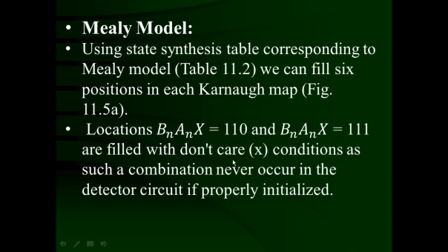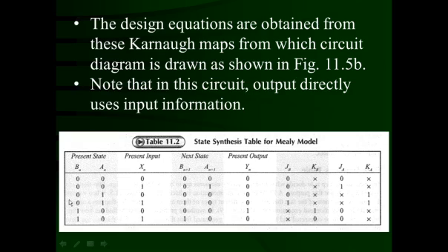are filled with the don't care X conditions, as such a combination never occurs in the detection circuit if properly initialized. The design equations are obtained from this Karnaugh map, from which the circuit diagram is drawn as shown in figure 11.5b. Note that in this circuit, the output directly uses the input information.